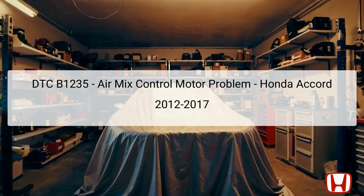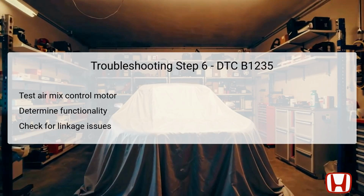In the final step of troubleshooting DTC B1235, you will test the driver's air mix control motor to ascertain its functionality. This step is critical as it directly addresses the heart of the issue. If the motor is verified to be operational, the next course of action involves replacing the climate control unit, as there may be internal faults within that component affecting overall performance.